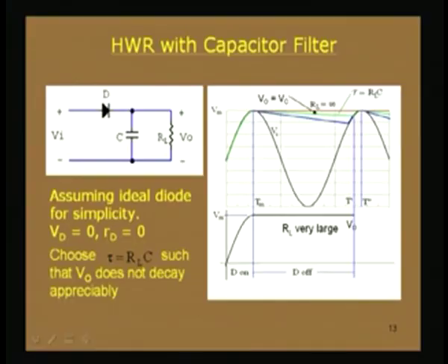So, here the capacitor is discharging and discharging, but you see that the input voltage is now increasing here, and after this point the input voltage becomes higher than the capacitor voltage. Input voltage is higher means the diode will be again forward biased, since Vi is greater than Vc, and conduction of the diode will take place, and therefore the capacitor will be charged again.